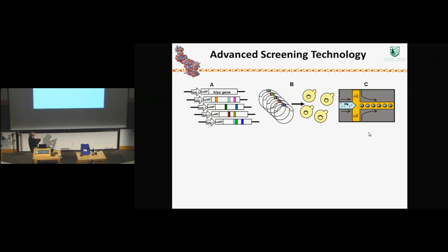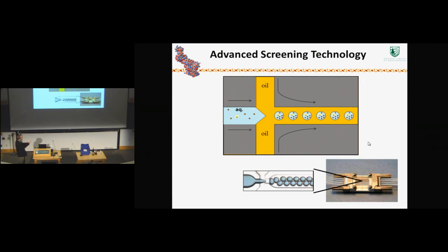All right, so this is a cartoon schematic of what the microfluidics might look like. And I just want to focus on that for a minute because it's an important point. So this is one of the chips, or similar to one of the chips that he's looked at. This is a close-up of the microfluidics channel here, and again, the cartoon schematic. So the scale that we're looking at here is that each of these little droplets is maybe 30 to 50 microns in diameter. And the way that this works is that we have an aqueous phase that's flowing onto the chip, and then at right angles we have an immiscible oil phase. And due to the fluid dynamics here at this junction, this aqueous phase breaks off into discrete individual droplets of controllable size. And the way that this aqueous phase is formulated is that there's kind of three key components that we put in there.